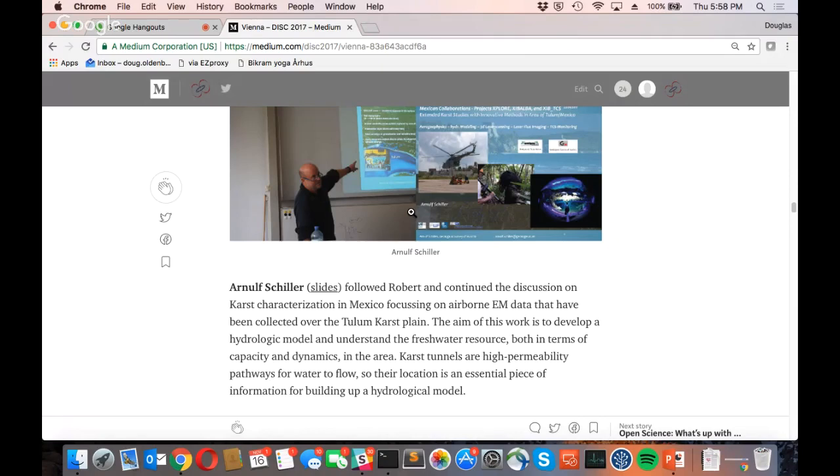What about waste dumps? The reason I ask about that is that the IP signature from waste dumps seems to be pretty consistent and often quite strong. So there's the potential for using IP and DCIP experiments to delineate between leachates and wastes. And also there's the potential for monitoring and remediation. Issue?